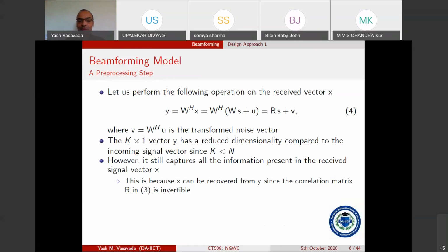And the Nyquist theorem promises us that as long as the number of samples is taken such that every second we are taking at least twice the bandwidth of the signal, so if we have 2B samples every second, where B is the bandwidth of the signal, then we are guaranteed to retain the same information that was there in that original continuous time signal. That is the promise of the Nyquist theorem. Something similar is going on here.